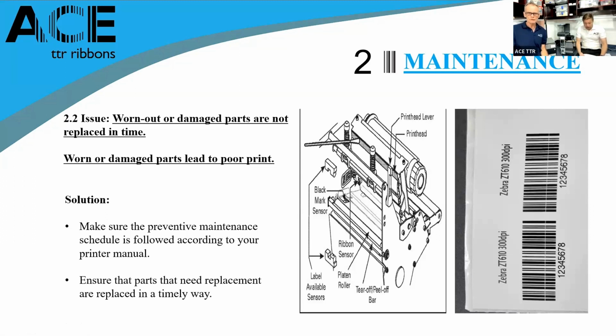So you're going to waste the material and you need to replace the print head in this case. Yeah, so I think that's right. That's probably one of the most common problems we've seen, a white line. I think we talk about creases later in the presentation, but one of the great reasons for a white line is dust or, at worst, a scratch. And with print heads being that expensive, it's frustrating to management that they weren't properly cleaned.